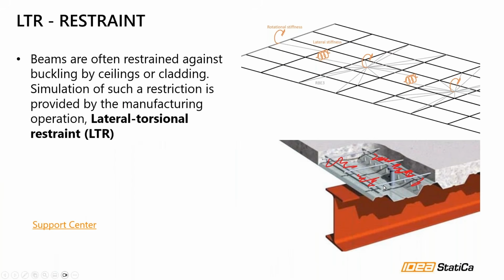And what about the composite slab? As I was mentioning, we are not allowing the import of the composite deck. If you would like to consider the design of just the steel part without this composite deck, you need to follow that the reinforcement in this direction needs to be disconnected, because if you are in the negative moment area, some cracks will happen in the deck, and you can just exclude this part from the simulation.